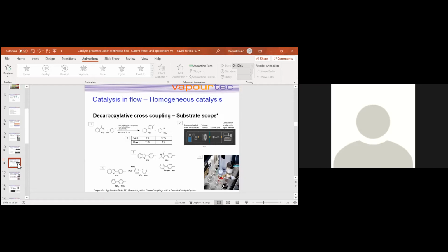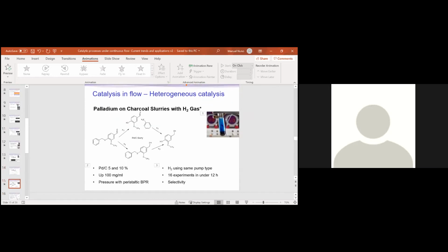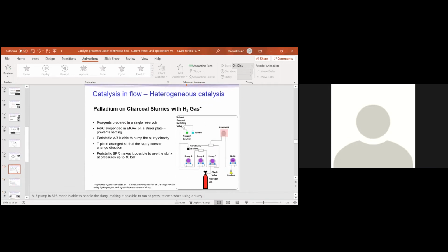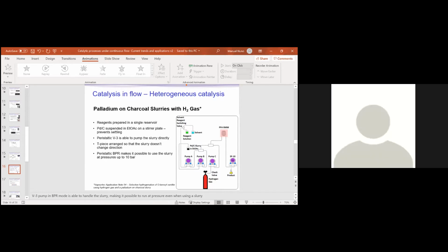Yeah, this is Eric. Just wanted to ask you about your application with slurry flow. The standard problem with slurry is you have to be able to separate the catalyst from your stream and reuse the catalyst. That is why fixed beds are so much easier to use.